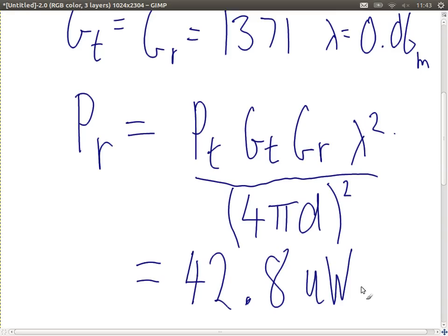We had an example a couple of weeks ago where if I talk very quietly, you cannot hear me because the signal you receive is very weak. It's too low for your ears to make sense of. Same as our receiver electronics. At our receiver device, we can use this knowledge to work out what's the minimum power that receiver needs to be able to receive, because we know how much power is lost across this distance of 1 kilometre.